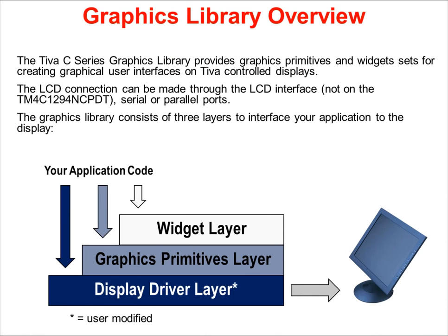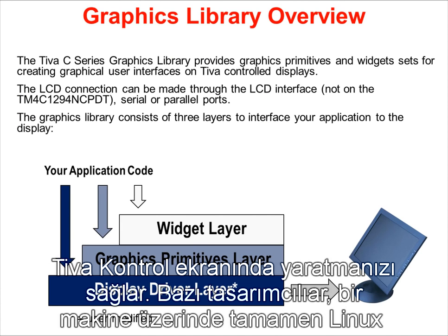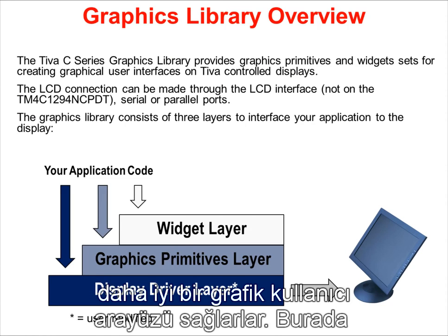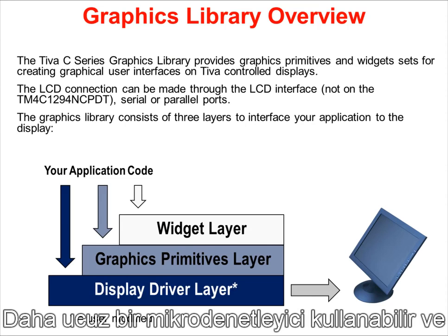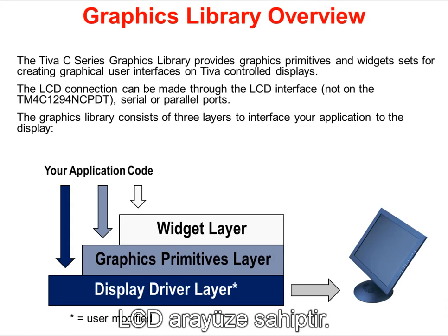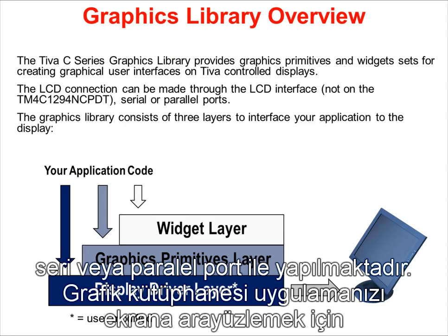The TivaWare graphics library provides you with graphics, primitives, and widgets for creating an entire graphic user interface on Tiva-controlled displays. Some designers will go all the way to using Linux on a machine just to get a better graphic user interface. Here, you can use a smaller, less expensive microcontroller and design your own GUI. Note that while some TM4C129X devices have an LCD interface, the one on the LaunchPad does not. The interface to smart displays is done through a serial or parallel port.